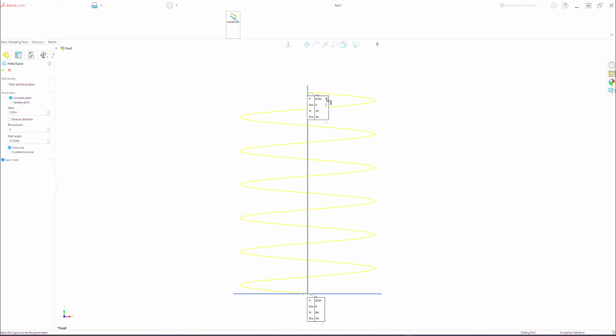And so we can control the distance, but again, as we control the pitch, the height changes. And so as a tool, in this case our project being a fidget toy, it's got to fit within your hand. So you've got to make a decision of how your overall height comes into play here. All right, so we're going to do a pitch distance of 0.60. I know it's kind of odd, but we're going to work with a 0.6 pitch distance here. And we'll choose OK.